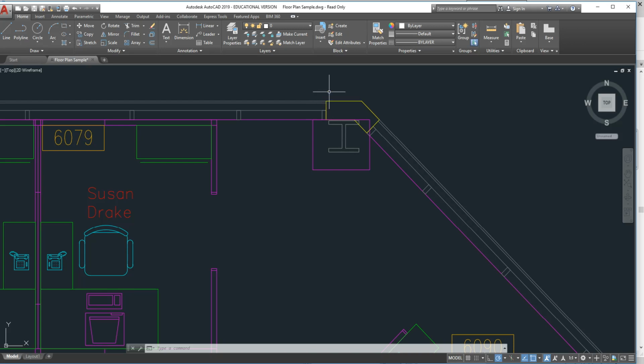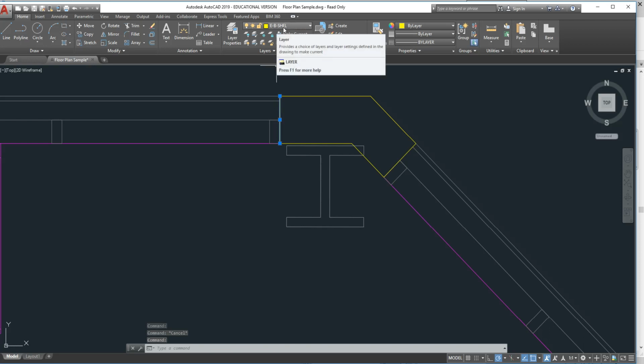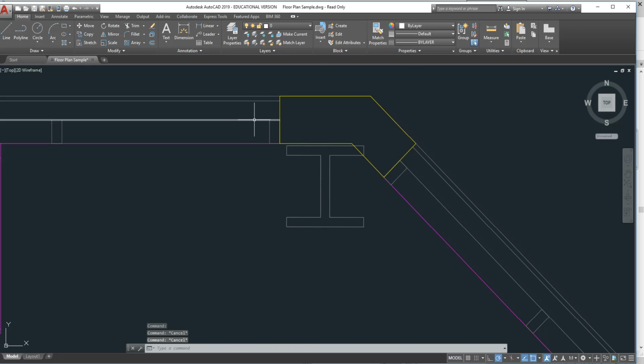is that there's a specific distance between this line, and we'll get rid of that, this line and this line, right? And we know that the color kind of tells us that it's an existing building shell wall, essentially. So the way that we know that things are walls in AutoCAD isn't because it's a three-dimensional wall like in a model. It's because we have items that have been offset a specific distance, right?